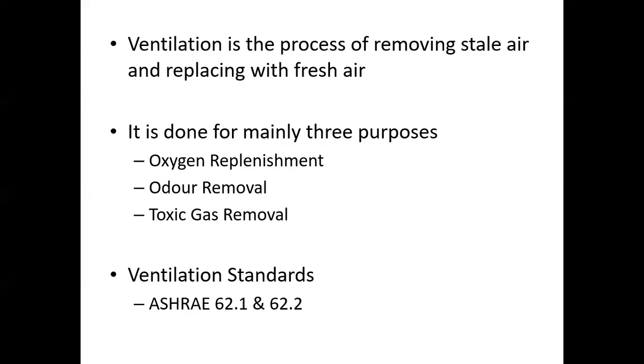For example, for each room you will have a certain fresh air requirement. If you have a project like a manager cabin, you need to provide 50 fresh air CFM. In the case of the office area, you need to provide 400 or 500 FA CFM. So where are you getting these values? You need to consider the area and do the calculation using the CFM per person method or the ACPH method. Whichever value is higher, you need to consider it as the FACFM value, isn't it?